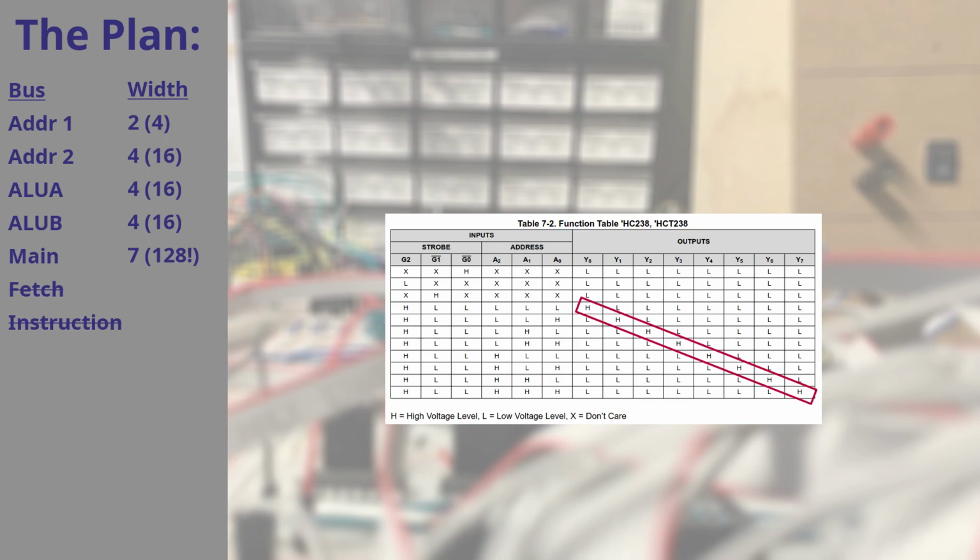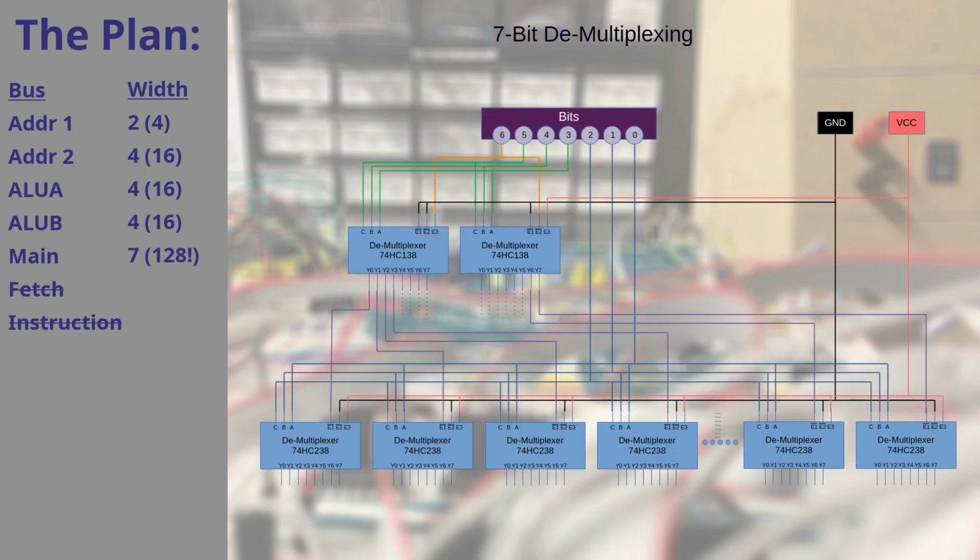Well, there is a 74HC238 3 to 8 line demultiplexer, which is functionally equivalent to the 138, with the exception that it does not have inverted outputs. So that shapes the signal the way that I want it going into the module, and I only need to worry about then inverting it on the other end. That's a good thing. Okay, so now I need to develop out for the emulator a 74HC238 IC.